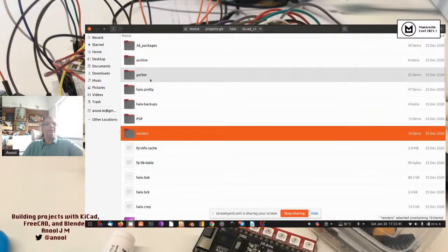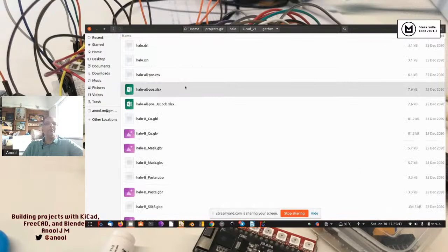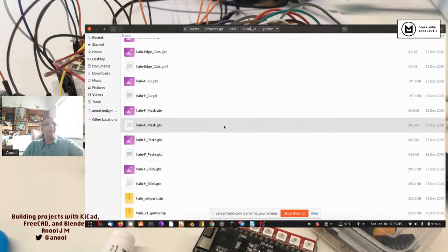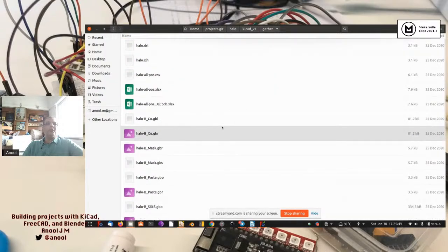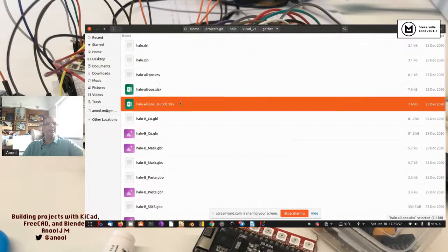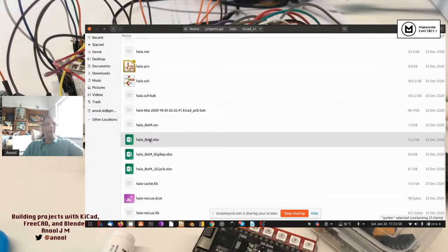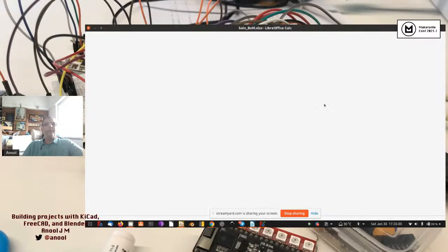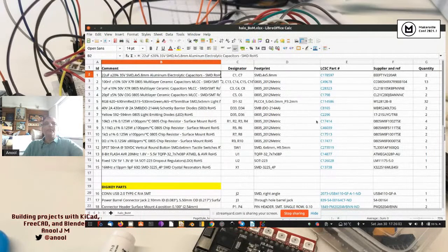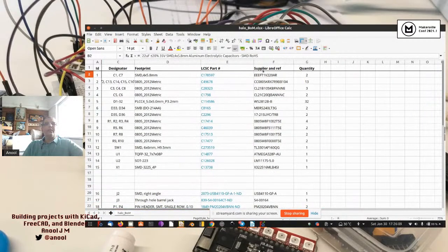And then obviously the final production output. Let's say you have a folder that's going to contain all of your global files. There will also be the position file over here, and somewhere in the main folder will be the BOM file. And as Amit and Akshay mentioned, the most important part is the supplier part number, or the MPN.